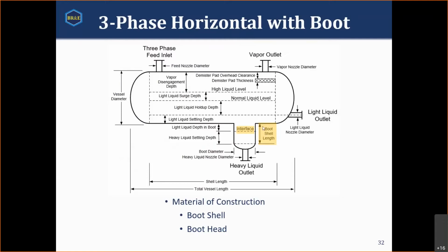And ultimately, you will get a volume for the boot that's going to be reported by this boot shell length, and that will contribute to the overall volume of the vessel, but the head space will not, similar to how the head space in the regular portion of the separator does not. And it's important to note that you will need to provide a material of construction for the shell of the boot and the head of the boot.